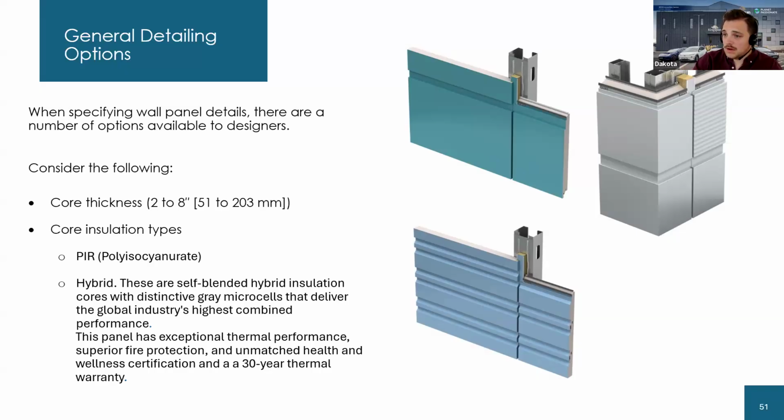It's also important to note that depending on what your fire performance wants to be, if you're hoping to achieve a particular wall, whether it's fire rated or something like that, you can actually swap this core out for mineral fiber, meaning that all the IMP manufacturers can get you up to like a 3 hour wall with like an 8-inch panel because that becomes a non-combustible material.